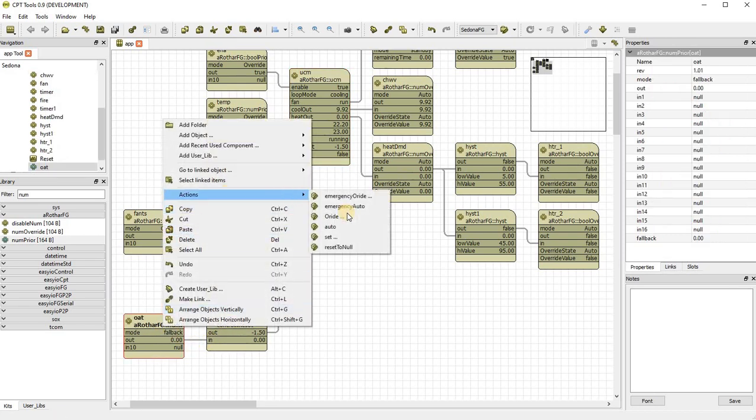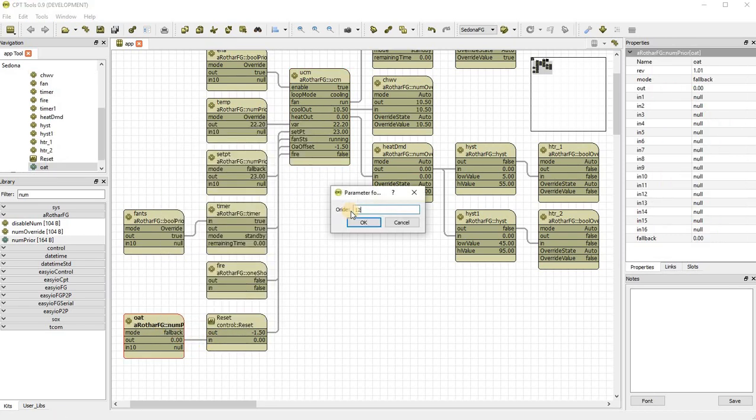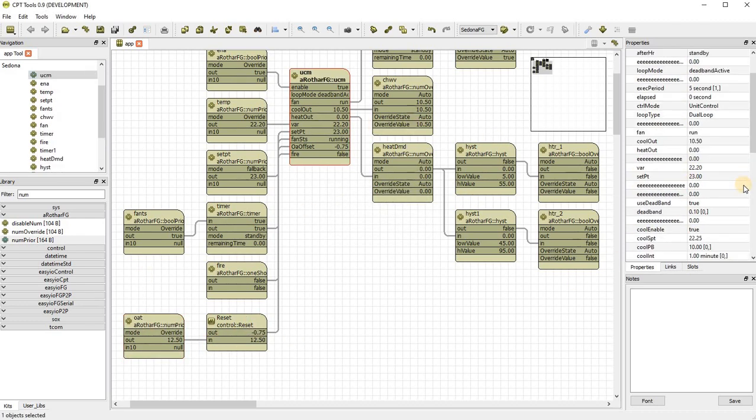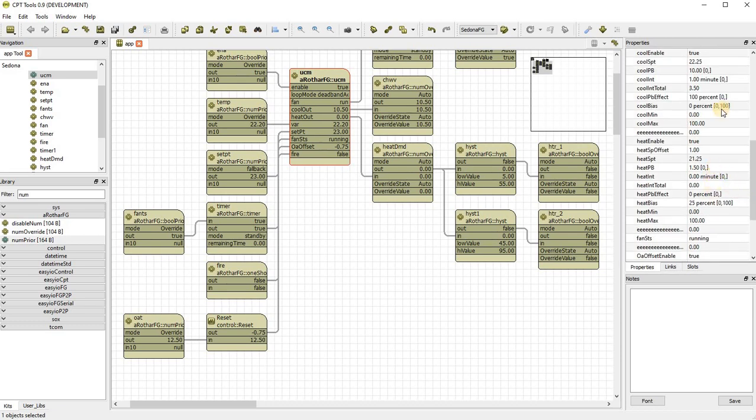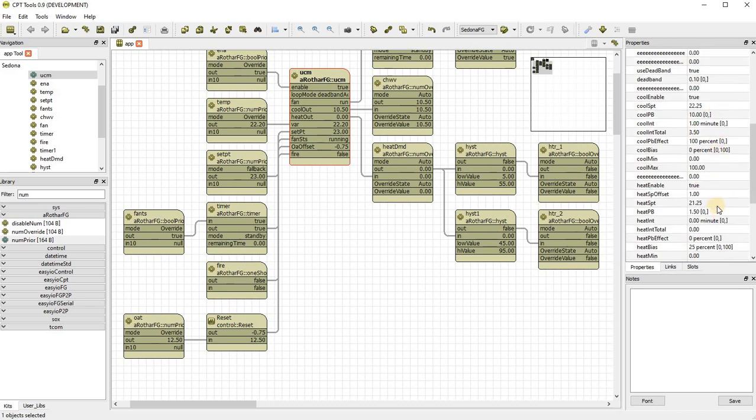So as our outside air temperature increases, if we went to 12.5 degree outside air, minus 7.5, then our cooling set point will be 22.5 and our heating set point will be 21.5. So you can see how this is impacting the set point without it actually adjusting the set point itself. The set point is still 23, but because we're outside of our design conditions, we're allowed to change the set points to manage our energy consumption of the plant.